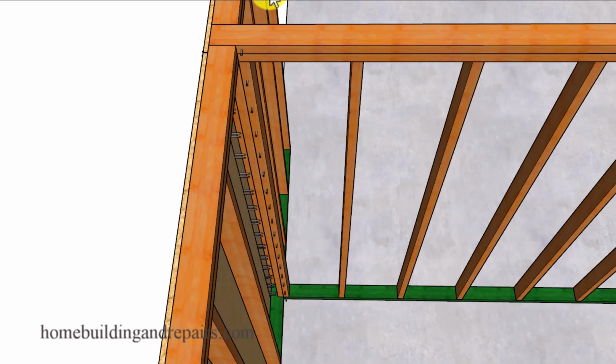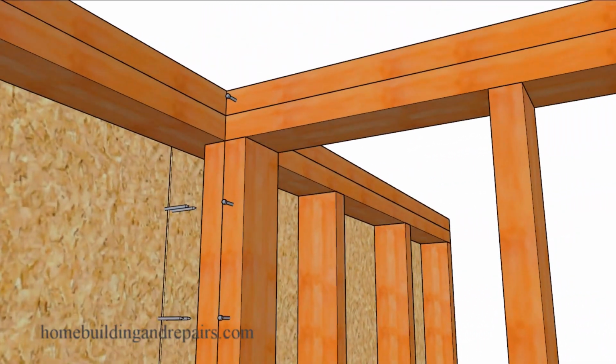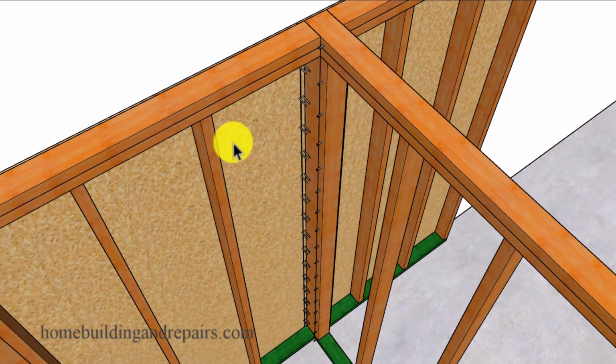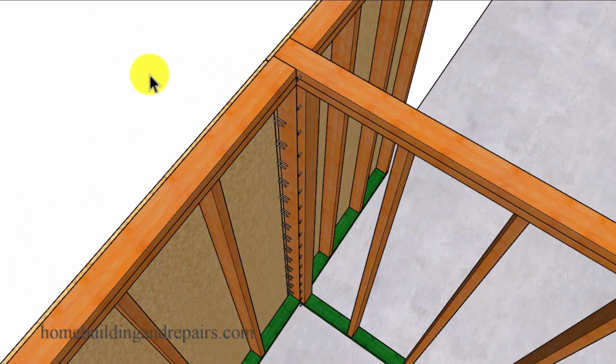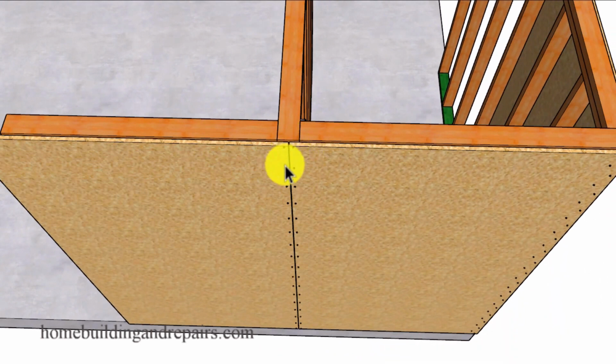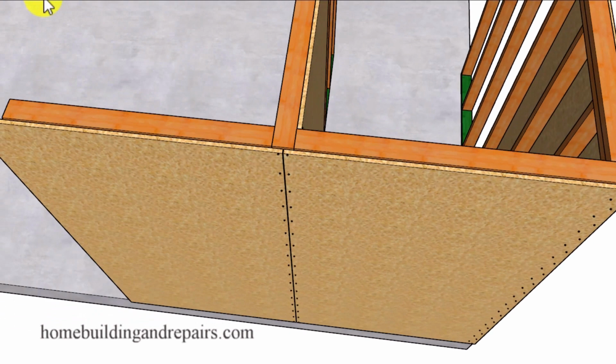And all we need to do to make this stronger is to install a 4x4 here and then run the shear panel over to here. And of course, we're going to have to redo the shear panel on the other side to make this connection stronger. You might not need to relocate the shear panel. Something like this might be okay, but why do it when all you need to do is break the shear panel on the center of the 4x4, so that instead of having 1.5 inches to nail the 2 pieces of plywood at the break together, you'll have 3.5 inches.